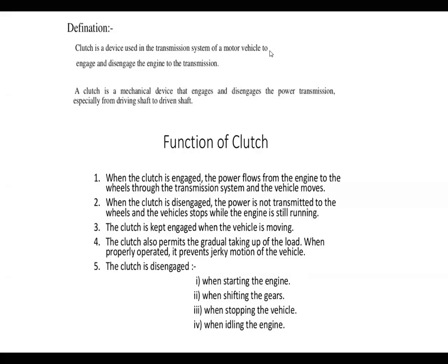So when should it be disengaged? Whenever it is at the starting of the engine, shifting of the gears, stopping of the vehicle, and idling of the engine. These are the main primary positions when the clutch is disengaged. And when the clutch is engaged, there is power transmission from the engine to the rear wheels. That is what we saw in the last class also.